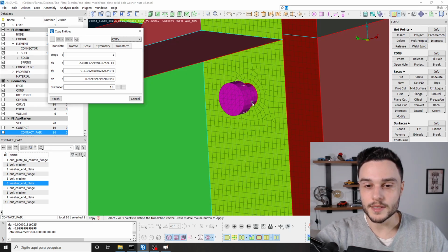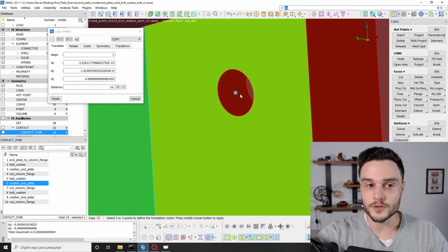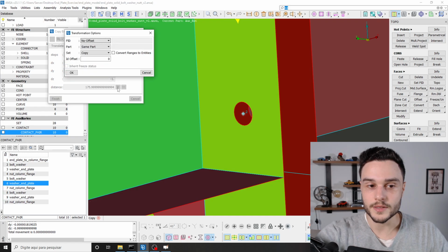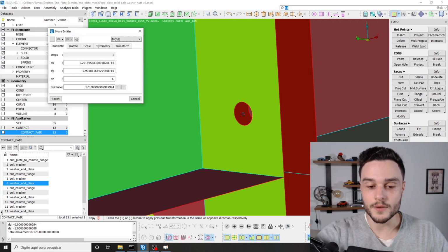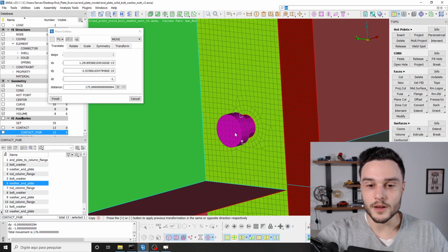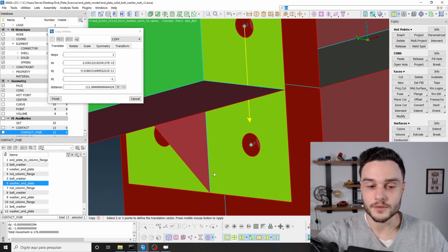And then let's hide the visibility of solid elements by unchecking this box here, volume. And also this box here, okay, for FEA entities. And then I want to create this copy from this point to this point. Plus, okay. And now if I have this visible and also this visible, you see that we have one new bolt here. Now we have the move tool again activated for these new bolts, but I want to actually copy and then deactivate these and these from this to this.